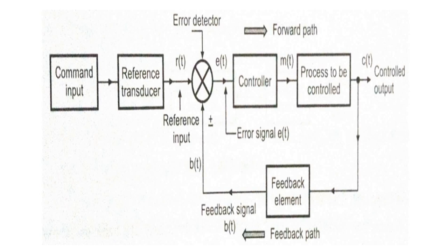Depending upon the nature of the controller and the plant, it is required to reduce it, amplify it, or change its nature, making it discrete from a continuous type of signal, etc. This changed input, as per the requirement, is called the reference input, which we get by giving the command input as input to the reference transducer. The main excitation to the system is called the command input. Whatever input we are giving is called the command input, which is then applied to the reference transducer to generate the reference input.